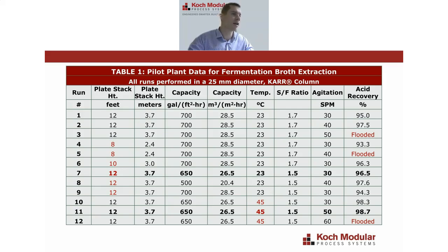Then we tried increasing the temperature, and this was the key parameter change when we were running this pilot test. By doing that, we were able to recover greater than 98% of the carboxylic acids. So here we really blew the spec away.